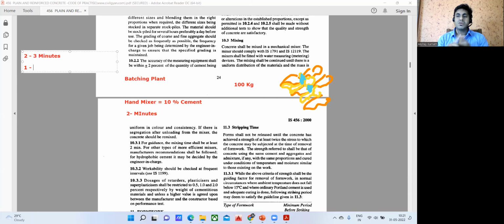You have coarse aggregate, you have sand and all. Now, there's a term called attrition and abrasion. What is attrition? If two materials of the same nature collide, we call it attrition. Abrasion is when two different materials collide, we call it abrasion, right? Now, since we have coarse aggregate, attrition is going to happen.